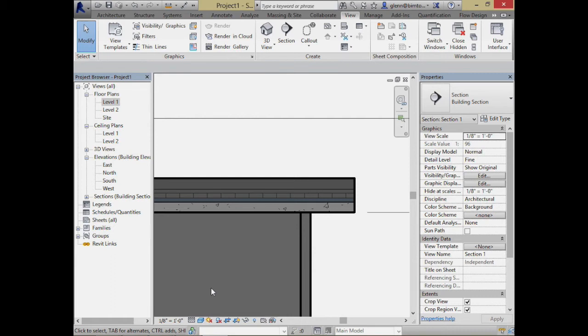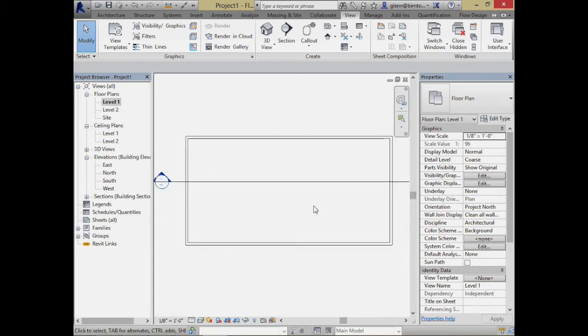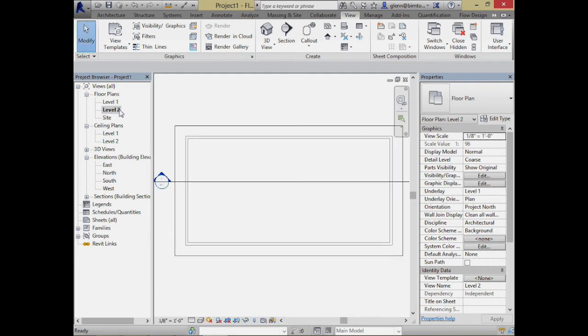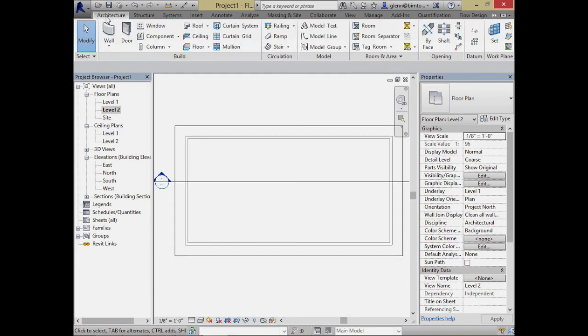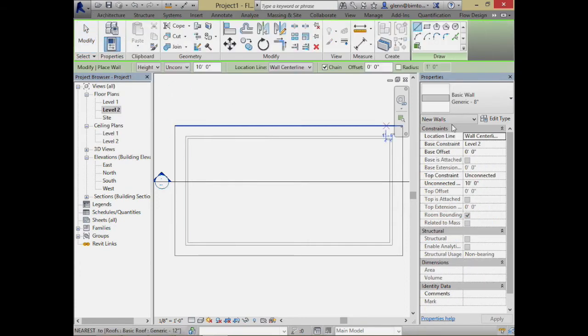You have to worry about that. You could try to berm it all down, but that doesn't tend to work out very well because dirt doesn't do a good job of staying where it's supposed to be. So what you may need to do with your green roof is put some sort of a boundary on the outside of it. Cap it off with some sort of wall. So what I might do in a case like that is put some sort of structural wall, maybe made of concrete, something like that.